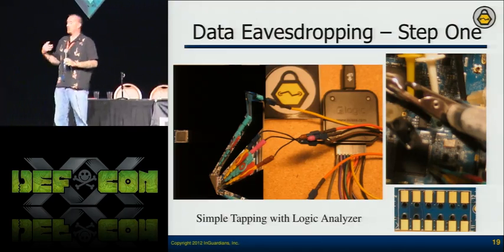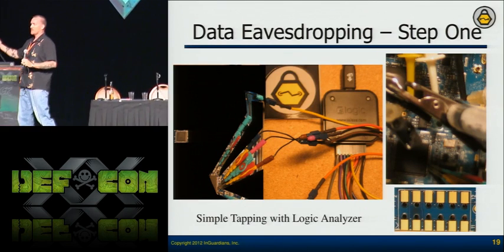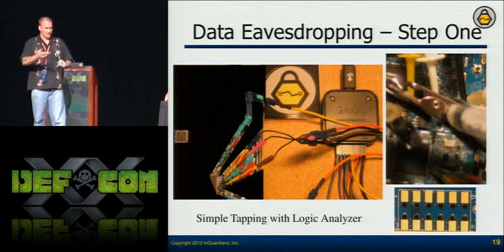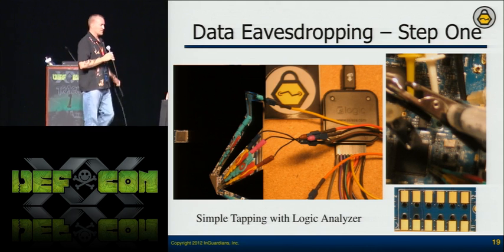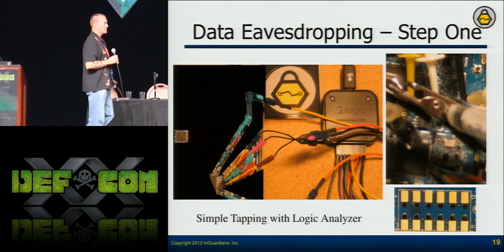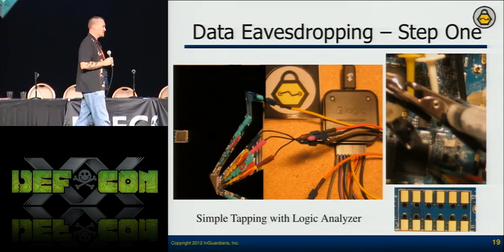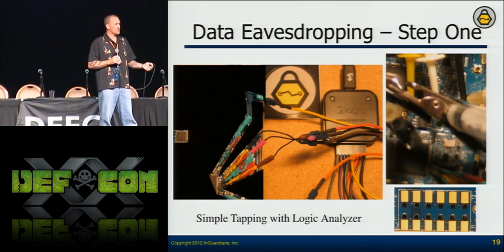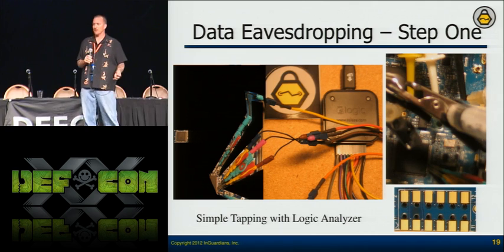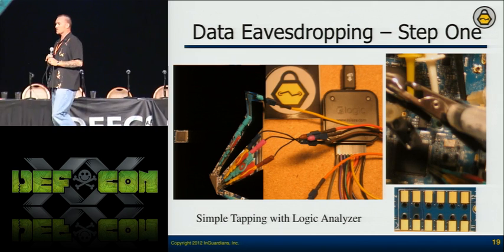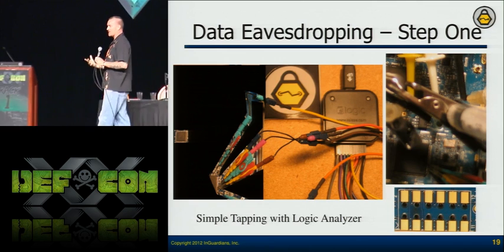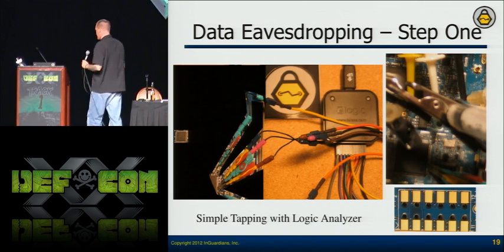So it's really tough. What we do is we look for debugging pads. Most of the debugging pads are for JTAG interfaces, to reprogram microcontrollers so that the developers have an easy way to push firmware up into the memory components. But when we're going board to board, sometimes we have those as well. And the board to board is going to show the communications that are passing between the NIC and the metrology board.